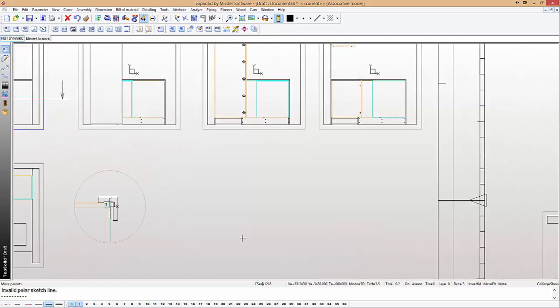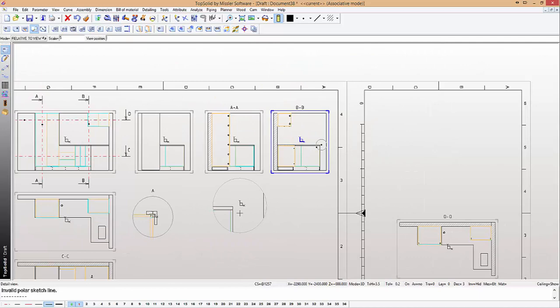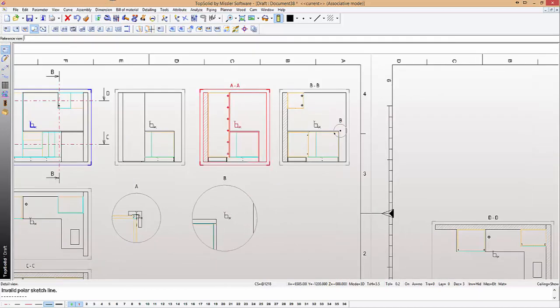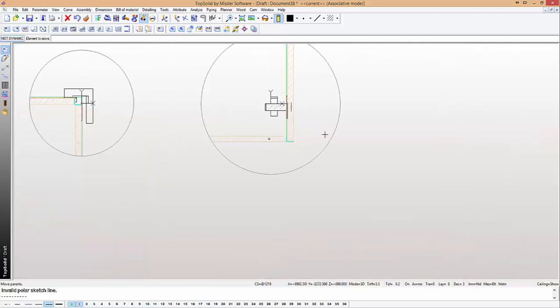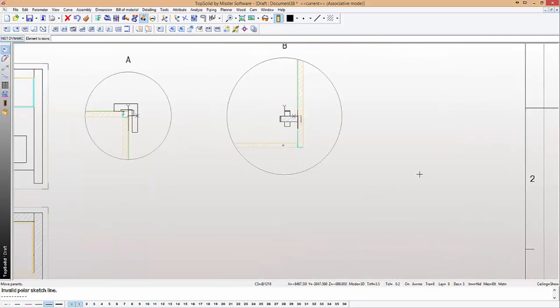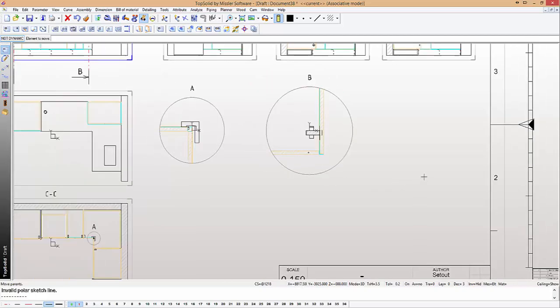Now let's create another section. Let's move up here. Maybe the section might be this corner here. We might say scale 1:5 once again, move it up here and bring it out. And once again, if you want to move it, you just move that section and say, yeah, we want to create a section up here. And again, it updates. And you've got all your machining information and so on in there in regards to our construction, which is a screw construction.